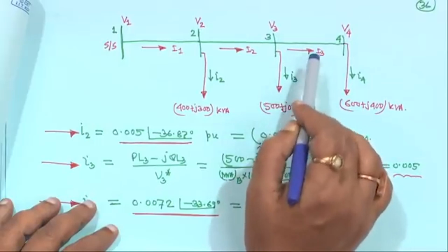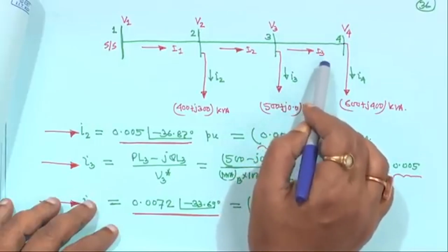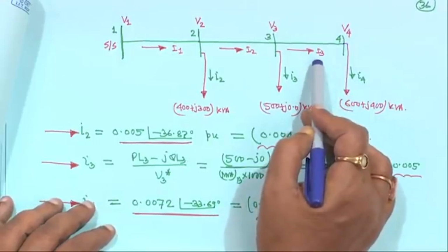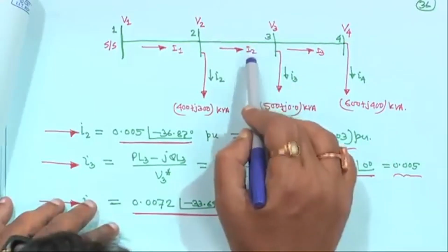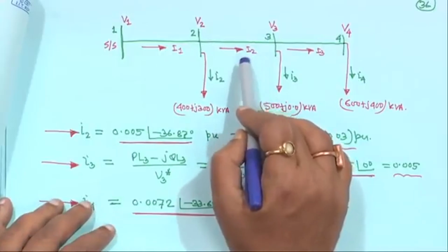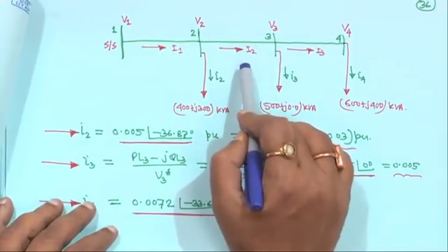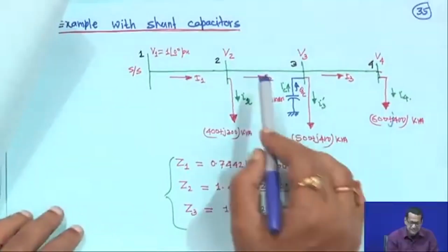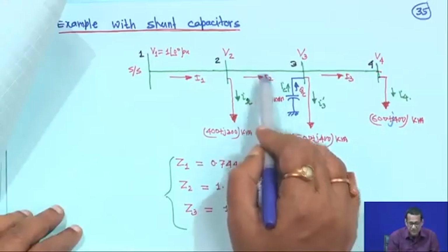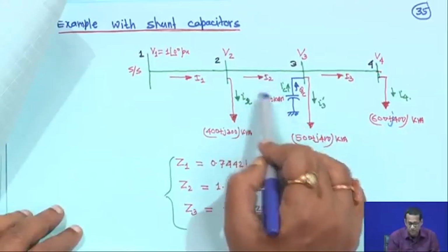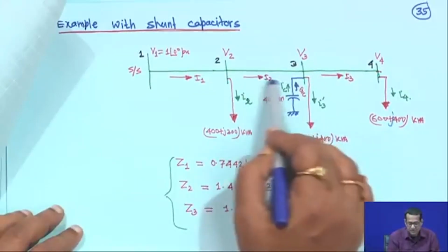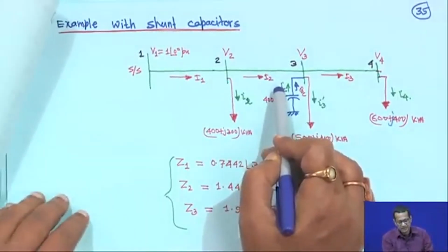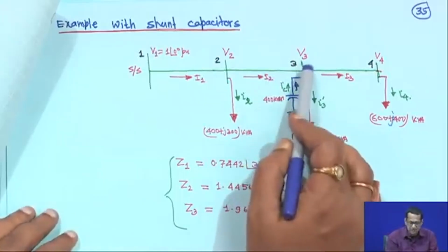But the power loss reduction in this branch will be only due to this voltage improvement, and that magnitude will be very small. But here the current will reduce, because if we take I2 equal to ID2 plus or minus jIQ2 and this IC is injecting, then the imaginary, or reactive, component of the current will decrease, therefore the voltage drop will be less. So, voltage will automatically improve.